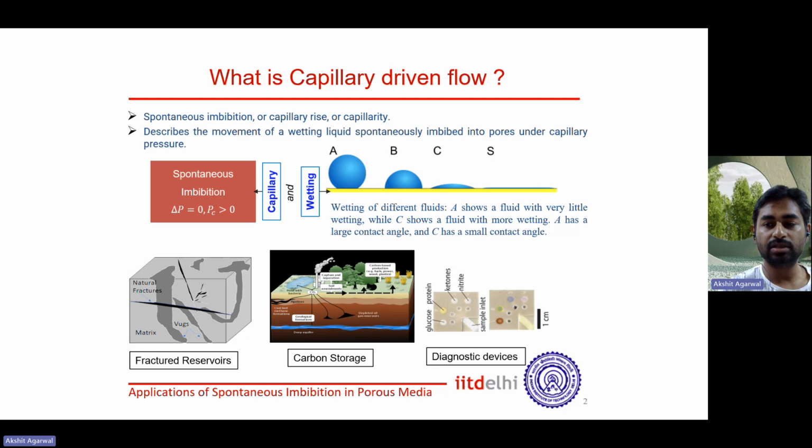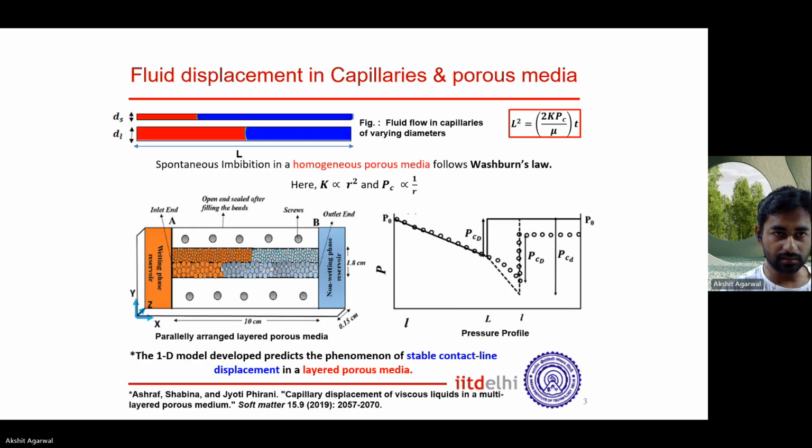Now I will discuss the theories and laws of fluid displacement in capillaries and porous media. Fluid flow in capillaries is governed by Washburn's law. Similarly, capillary-driven flow in homogeneous porous media also follows Washburn's law, which states that the square of the length of imbibition is directly proportional to time. Washburn observed that the rise of fluid is faster in a capillary of larger radius, as you can see in this figure.